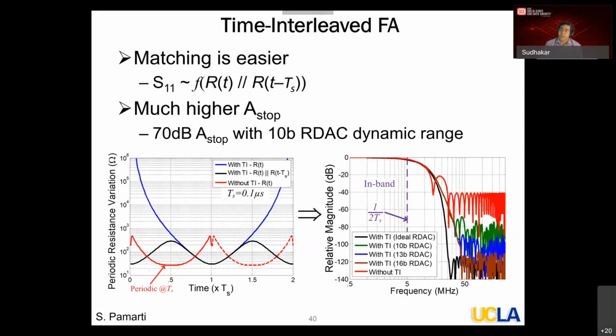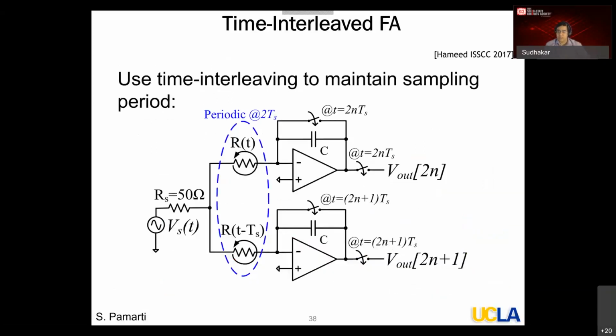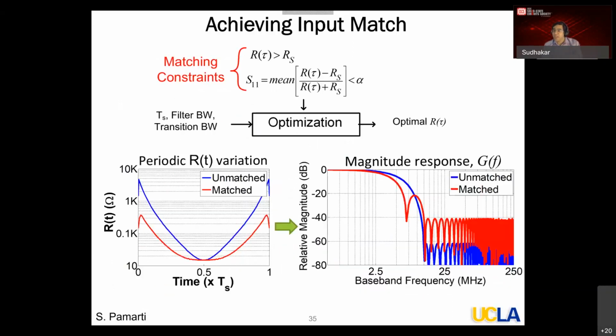Now, let us say that you do this calibration once, and with temperature, things change. If the R changes with temperature, then clearly the coefficients can change. But that is not that bad a deal. If the Rs are also going to change, arguably, then the whole thing will scale accordingly, and it is not a big deal.